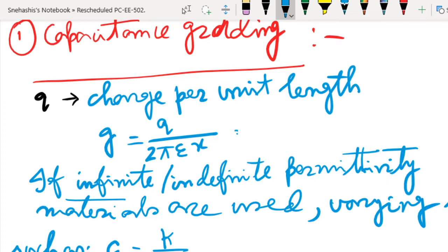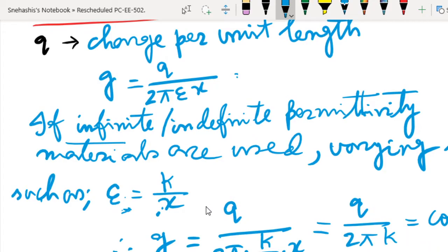Basically, for a particular operating voltage, the overall size of the cable becomes minimum, and this looks quite good, but practically it is impossible to place an infinite number of dielectric material layers with varying permittivities. Normally 2 or 3 materials are used in general.